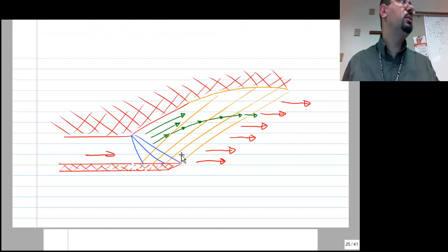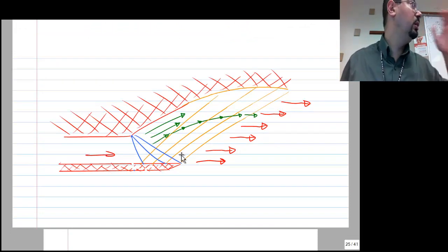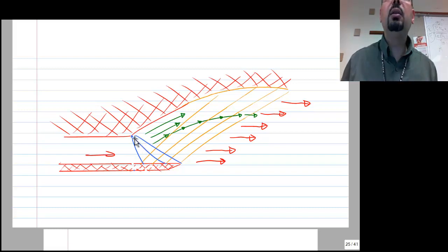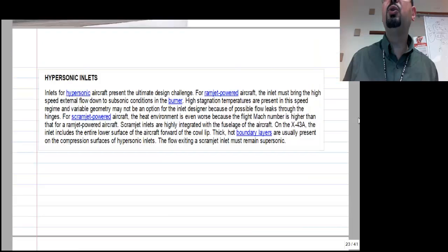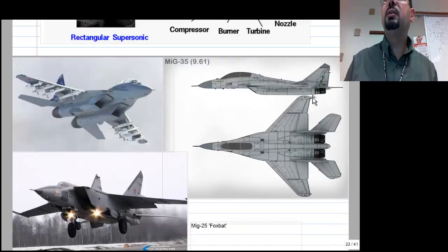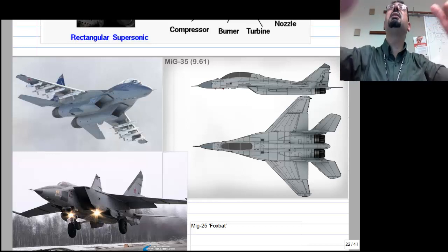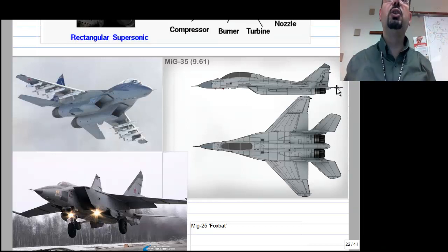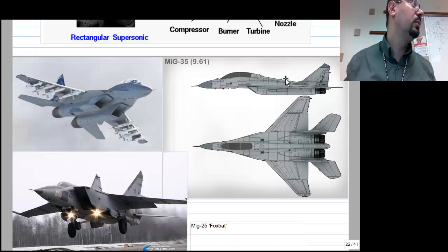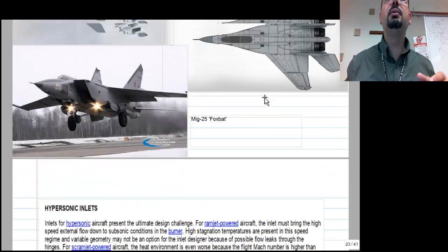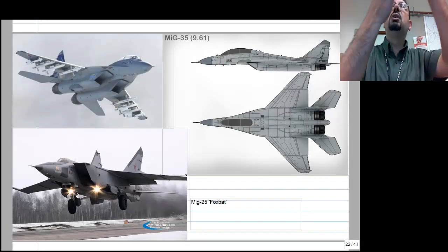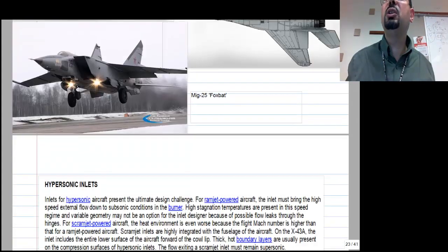So you will leave the combustor section with very high temperature, and then in all those jet engines, what is the point behind all those jet engines? You want to generate very high velocity so that you can get the thrust, right? You want to basically send the flow out at very high velocity. And so you build that pressure in the compressor, you build the temperature in the combustor. The combustion usually happens at constant pressure. Okay? And then you expand in either a convergent nozzle or a convergent-divergent nozzle like a rocket engine.